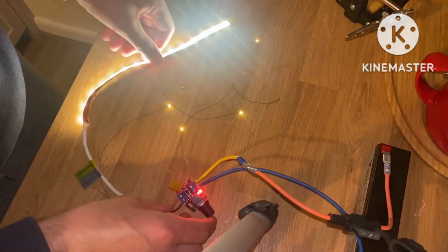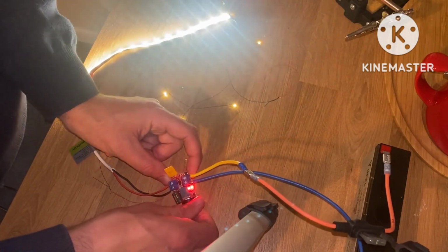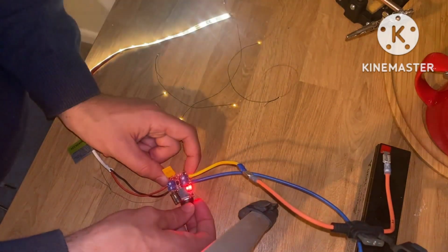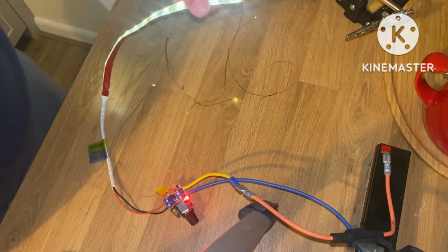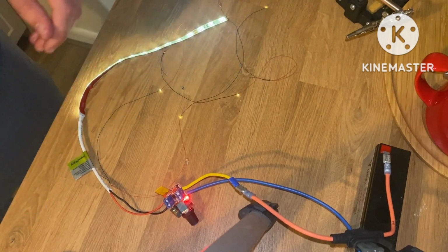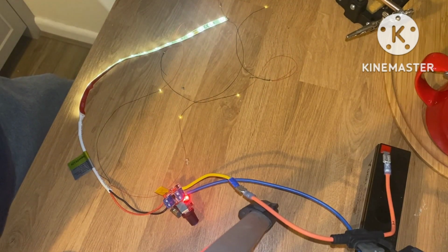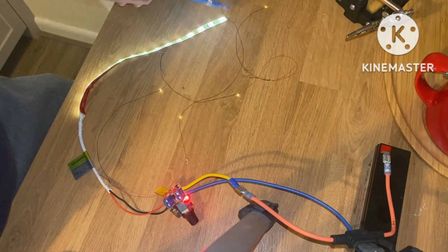There we are. And you can see that the PWM gives me dominion over how bright these lights are, just as I would like it to. But we can see that we've got a string of LEDs connected up into my LED strip. And as I say, it is really that simple. If I wanted to add more strings of LEDs, I could do. Just copy exactly the same thing again. Resistor, 4 LEDs, and then solder it onto your LED strip.